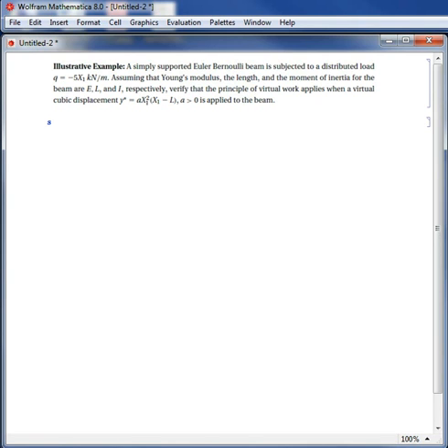So I'm going to call the solution as S, solve the differential equation, as we've done in the beam equation, EI multiplied by the fourth derivative of the displacement. This is equal to Q, and Q is equal to negative 5 multiplied by X. I'm going to make everything a function of X. The boundary conditions are y of 0 is equal to 0.